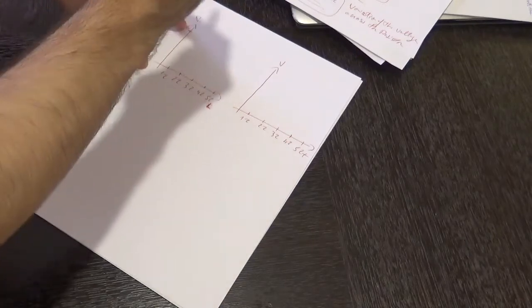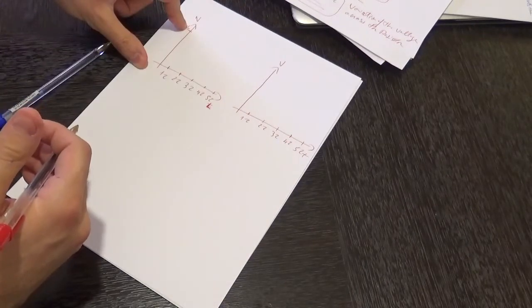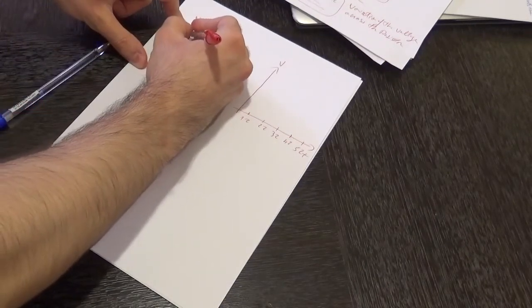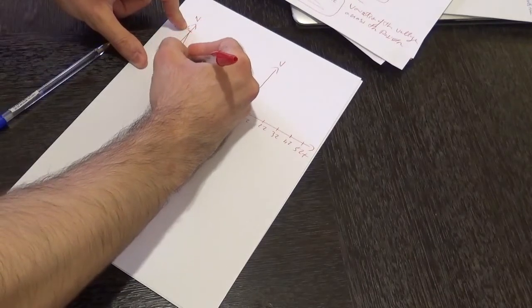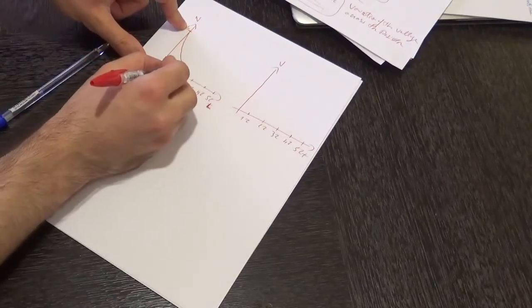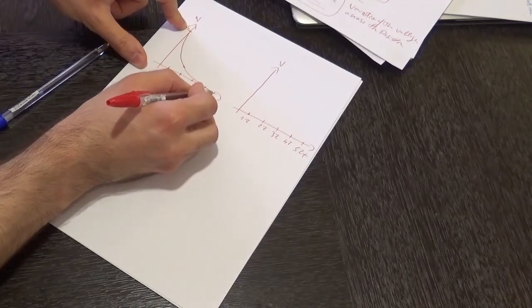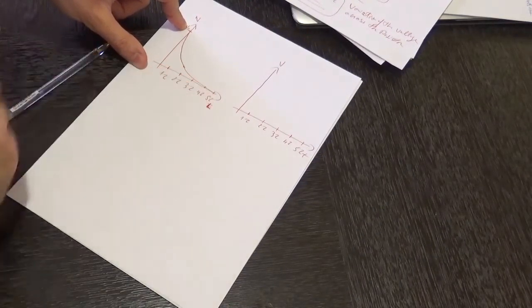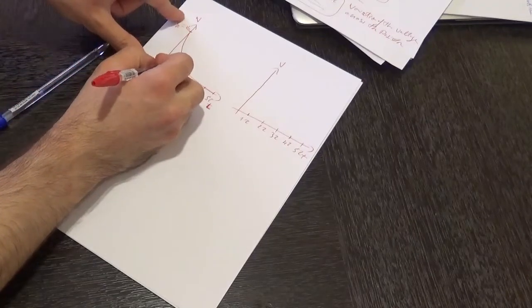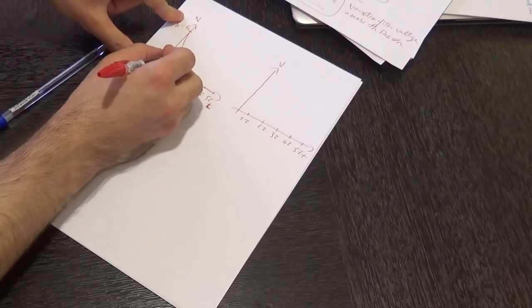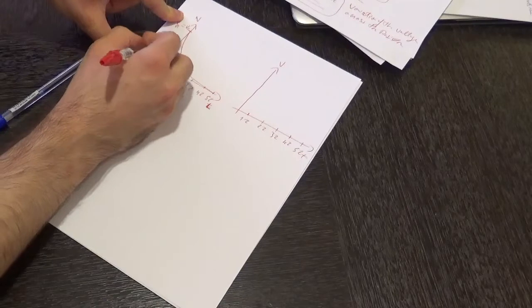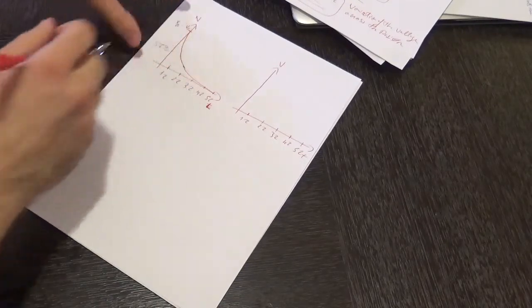And then we undergo a discharging process across the resistor. So over here we have an exponential decay that carries down until the voltage across the resistor drops to 0 after 5 tau. And after 1 tau we have a certain drop in voltage down to 37% of the maximum value of V0.